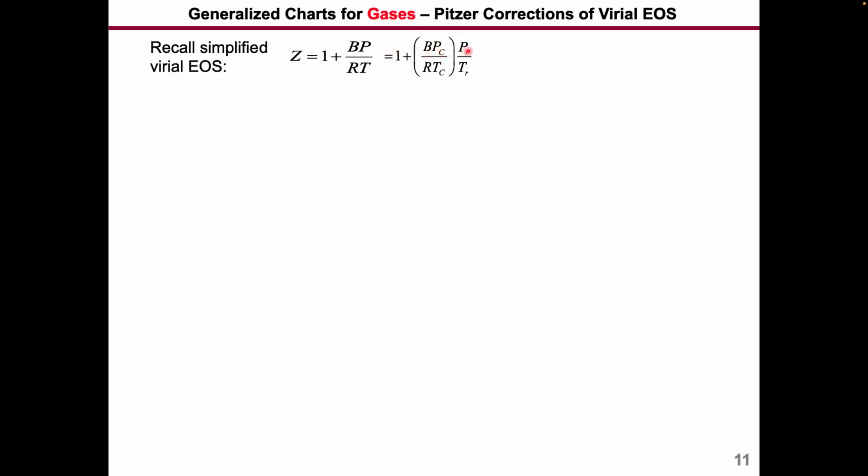So P is equal to the relative pressure times PC, and T is equal to the relative temperature times the critical temperature, okay? And then you can combine these things. Since these are substance-dependent TC and PC values, you can combine everything together. So basically this B hat is going to be a material-specific constant, okay? And again, people have already measured that for you, okay?